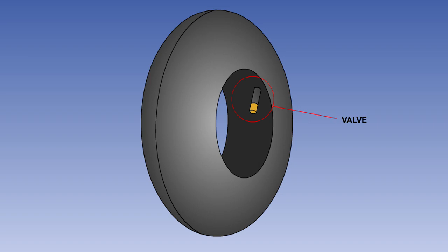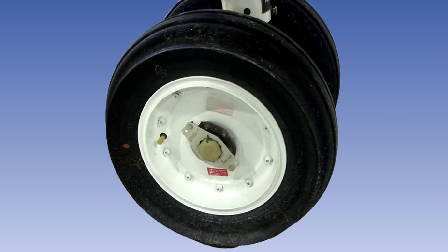Whether the tyre is fitted with a tube or is tubeless, an inflation valve is required. In the case of the tyre with a tube, the valve forms part of the tube installation, whilst on a tubeless tyre, it is fitted directly onto the wheel rim with a rubber sealing gasket. Each inflation valve is fitted with a non-return valve. The valve core is not considered to be a perfect seal. Therefore, the inflation valve must always be fitted with the valve cap. The valve cap also prevents dirt from entering the valve.